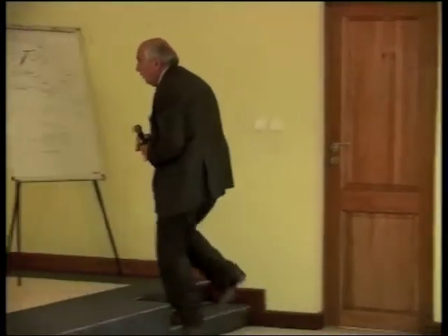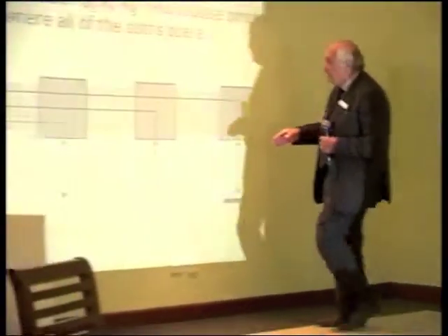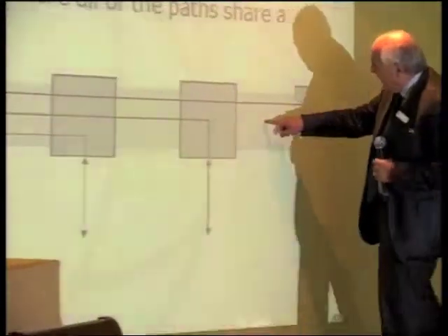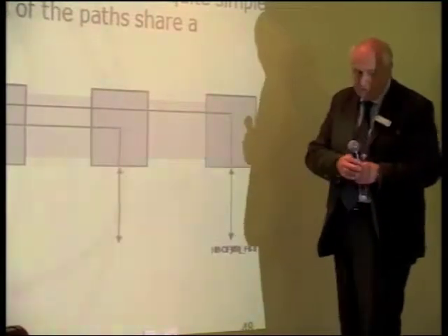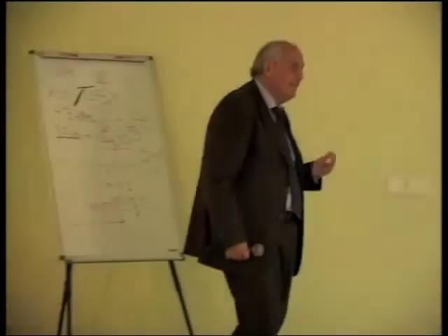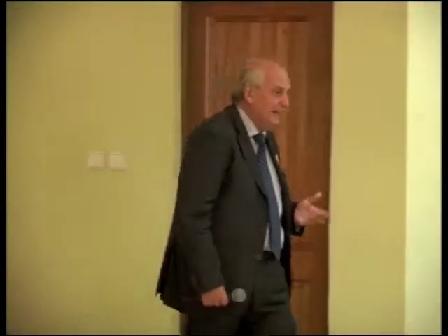We just evaluate the maximum degradation, which is the degradation we get when we traverse all the optical add and drop multiplexers. This means that we can rearrange all the paths. For example, we can drop the wavelength here and we have this one going through, but the degradation has been calculated, has been evaluated at the beginning.